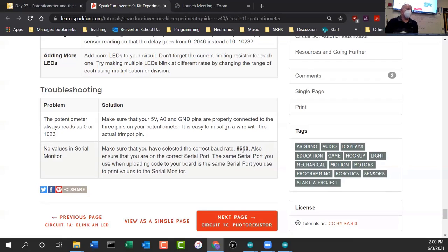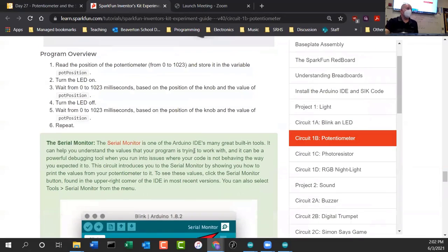Now, back when I was younger as a programmer, I had to create serial communication protocols just like this. But now we know what a potentiometer is. We know how to convert from an analog signal to a digital signal using an A to D converter. There's an A to D converter built right into your Arduino. It takes that analog signal and converts it into a number that the computer can then use in its calculations to set, in our case, the speed of the blinking.